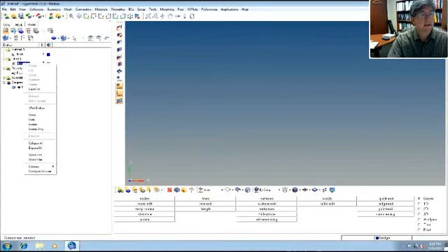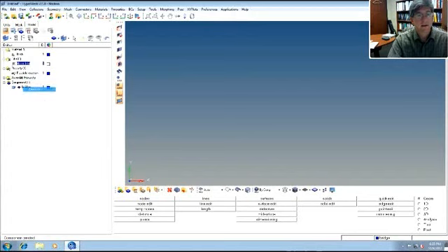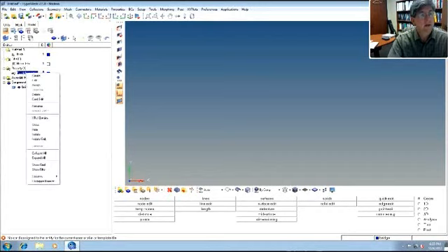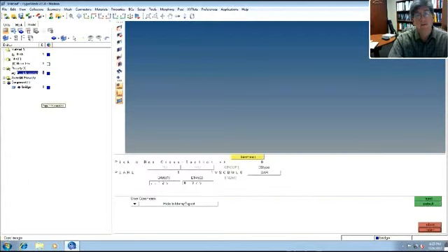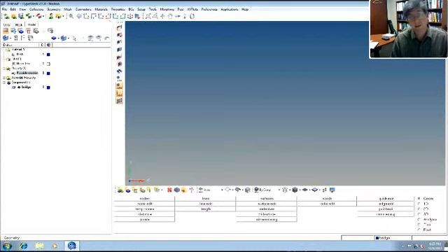You can actually edit this, card edit. Oh, that one didn't support that one. Okay, well, sometimes you can edit those. But you can see, like, for the popsicle cross-section, if you right-click on it, you can do card edit, and the actual card pops up, and you can edit those properties, okay? Just like you would. When people first start doing this, they think it's very bizarre, because they don't understand how the Nastran input file works. But if you're comfortable with those types of input files, then you can see it actually supports it quite nicely.